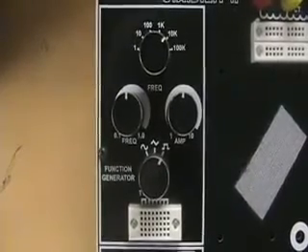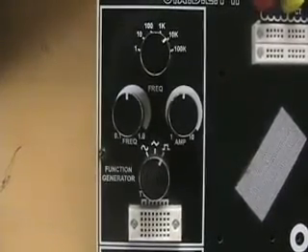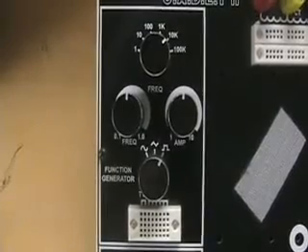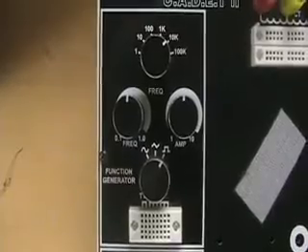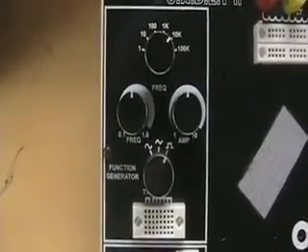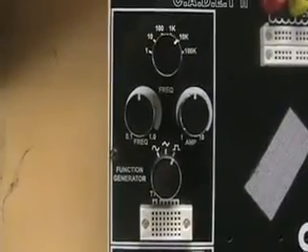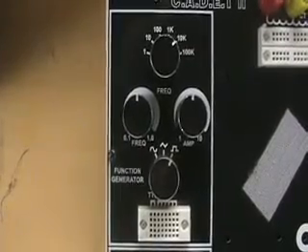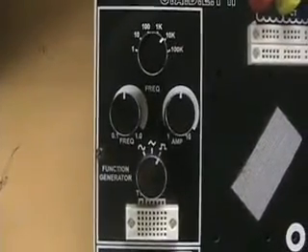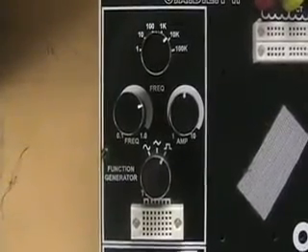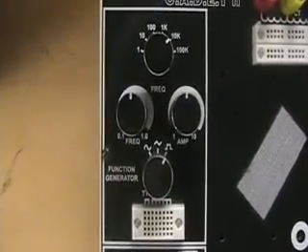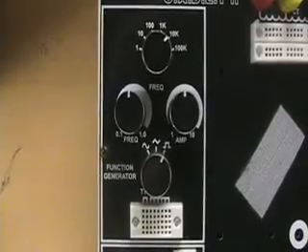After you select the waveform, you must set the frequency of the wave. The left knob and the center knob control the frequency. The left knob multiplies the setting of the upper knob. For example, setting the upper knob to 10K and setting the left knob to 5/10 will produce a frequency of 5 kHz. If we increase the setting of the left knob to 8/10, we will then produce a frequency of 8 kHz. Finally, you can use the right knob to set the amplitude of the wave anywhere from 1 volt to 10 volts.